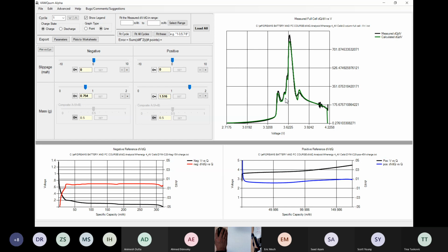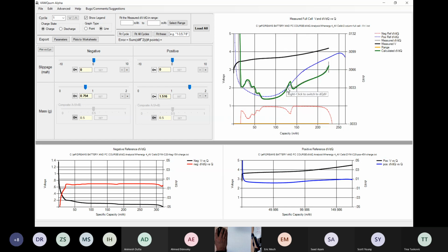We've talked about that in the EIS section. But if you plot dVdq versus Q, the voltage curve just shifts down by a certain amount due to the increased internal resistance. It doesn't change dVdq versus Q at all. So fitting dVdq versus Q is impedance growth independent to first order, which is a good thing.